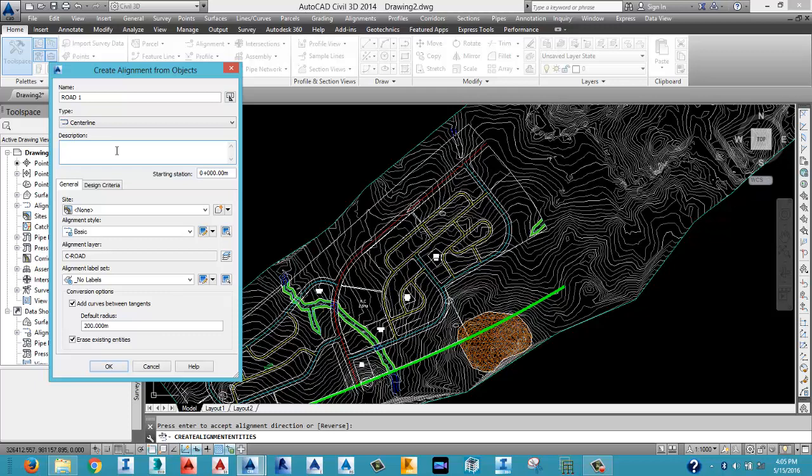But sometimes you want to design a road whose chainage doesn't start from 0, maybe a continuation of a particular road corridor, so you input the end of that corridor here. The numbering then continues from what you inputted. Now it is left at default, which is 0, and the next one should be 1, and it keeps counting like that.